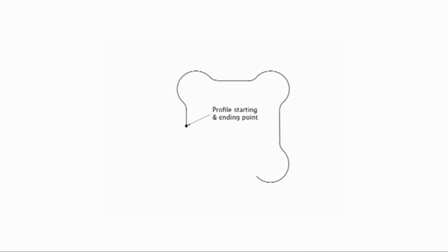Since this will be a custom profile that we create, it will be necessary to plan our entry-exit point on the profile and direction of cut now before beginning any programming. For our demo, we will start the profile at the left side center edge and then program our points in a clockwise direction around the profile until completing the shape. The process of programming our part in the Fagor profile editor will follow this sequence of steps as an example.